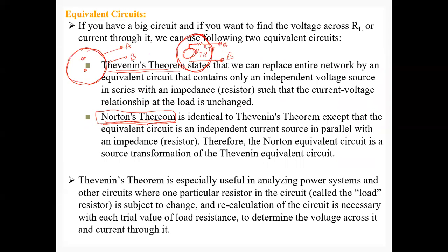So when is this Thevenin theorem useful? The same applies to Norton's theorem also. I wrote this for Thevenin's theorem. Thevenin's theorem is especially useful in analyzing power systems and other circuits where one particular resistor in the circuit, called the load resistor, is subject to change.